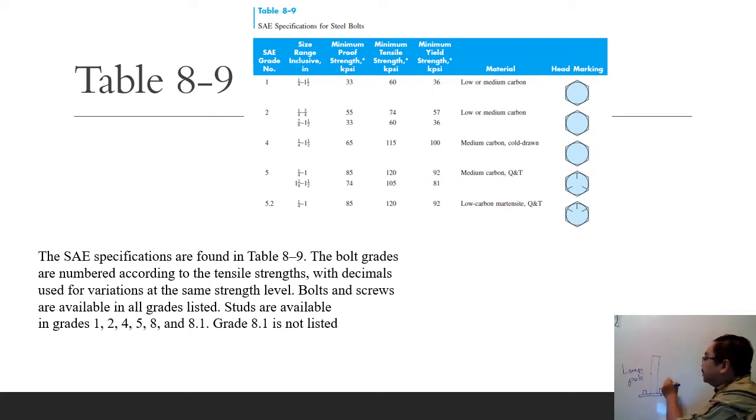Of course these have higher tensile strength, so the grades will be higher in that table. So you can choose your bolt according to your application. Do not choose over strength, because it is a waste of money if you are choosing the wrong specification.